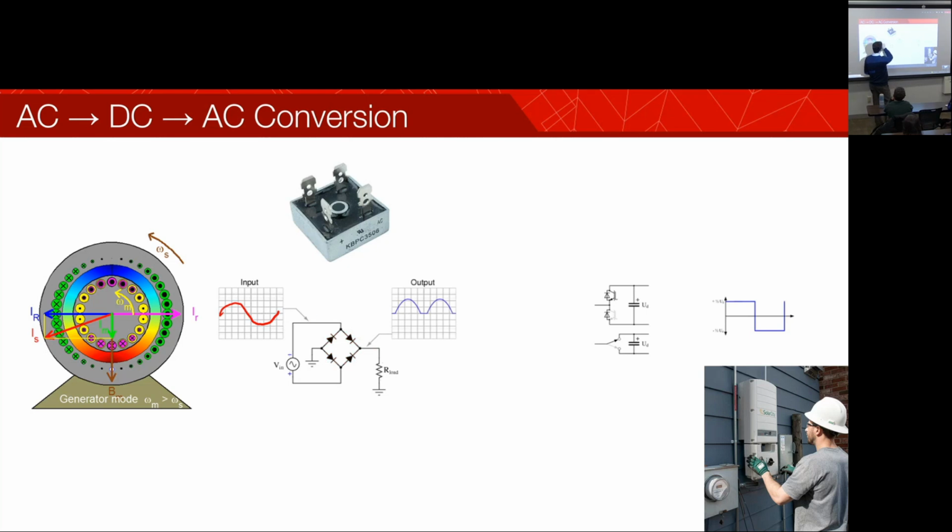So we can take an AC waveform, turn it into an always positive waveform, and then if we put a capacitor around that, we can essentially take the average of that. And so now we have this average of this bumpy waveform, and we can turn this always positive signal back into an AC waveform. How do we do that? We can do essentially the opposite of what this is doing. We can take this always positive waveform, that's buffered by these capacitors, and just flip it back and forth by these two switches here.